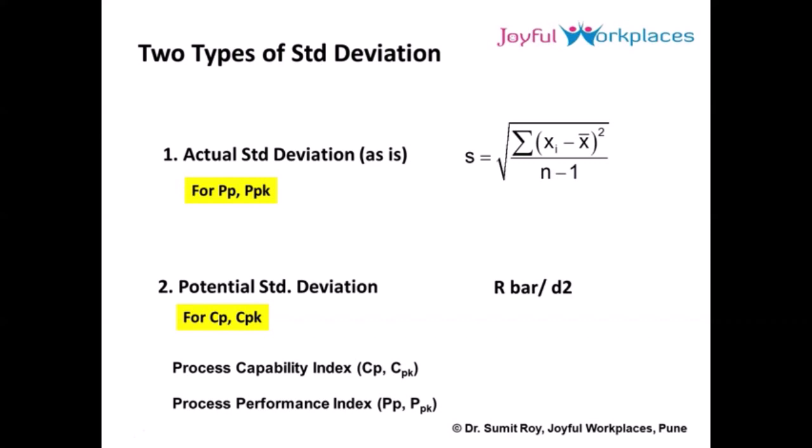Now, those of you who have learned process capability studies earlier, or how to plot an X bar R chart, would know that one methodology of calculating standard deviation is collecting 3 to 5 samples in a short span of time. Say, for example, that in an hour, every minute, one product is manufactured, say turned by a lathe machine, for simplicity.